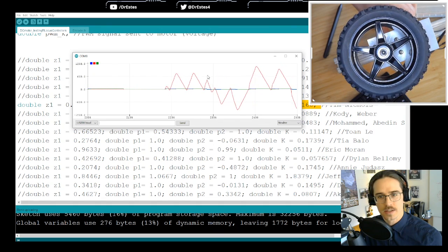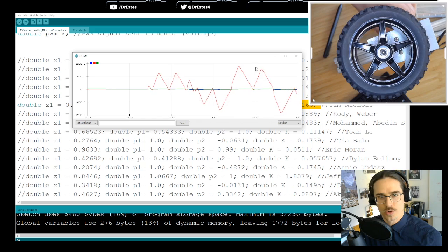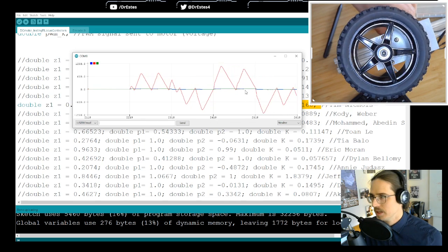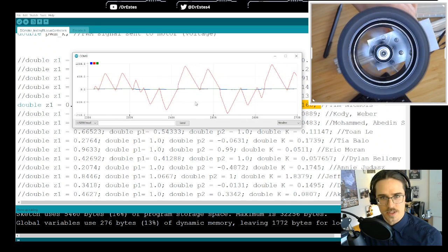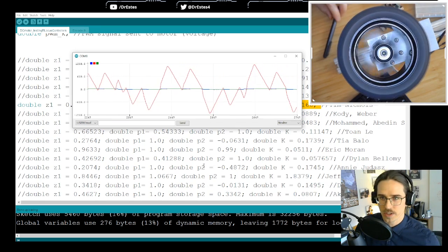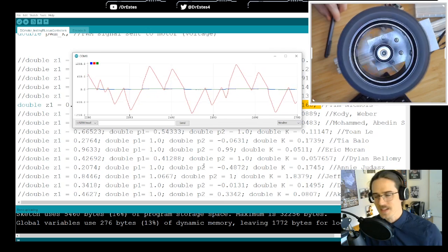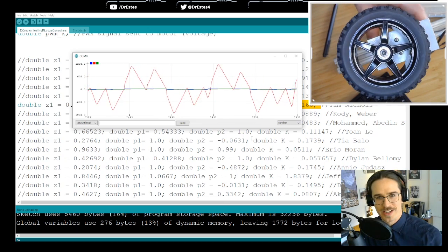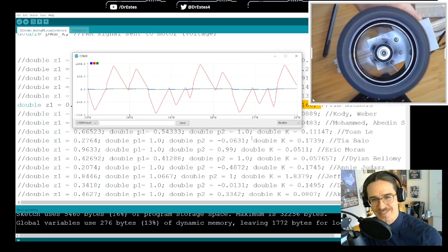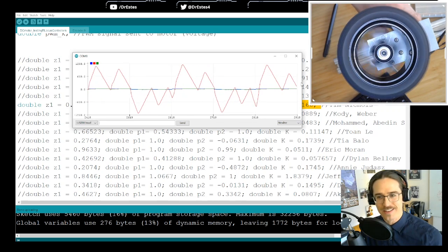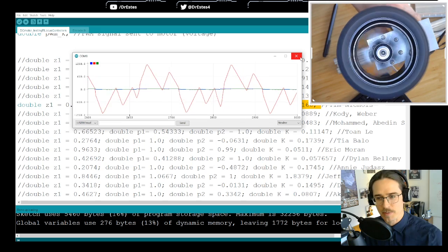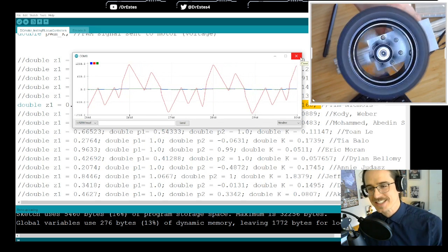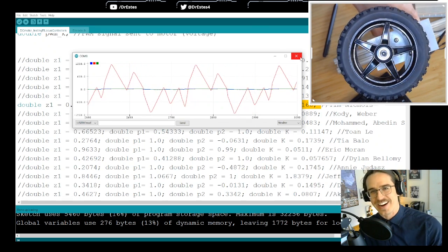This red line is the voltage that the controller wants to send to the motor. It wants to send like a kilovolt, which there's stoppers in. I mean, I don't have a kilovolt here, so it's not going to do it. There might be a typo in your parameters. A gain of 5 is pretty steep. Okay, this is to be expected. This will happen with some controllers. This is great for a drag race burnout.